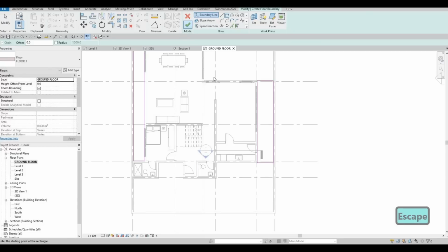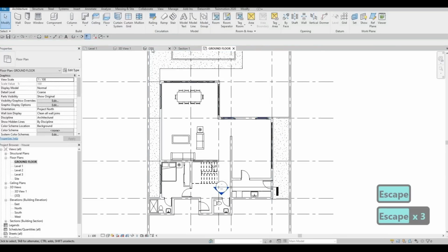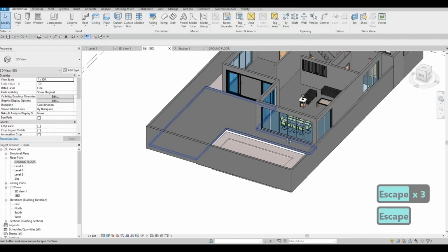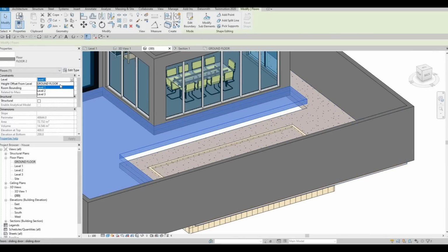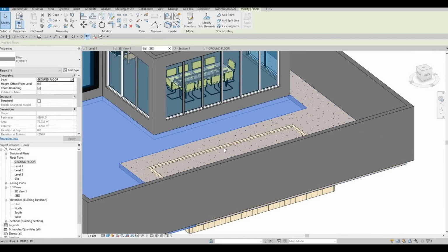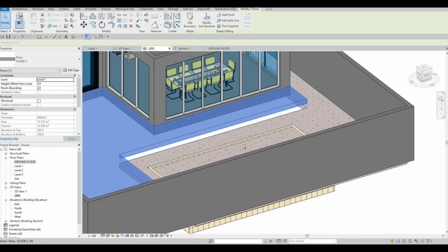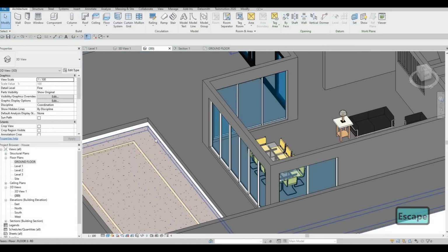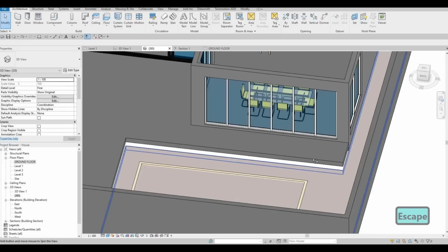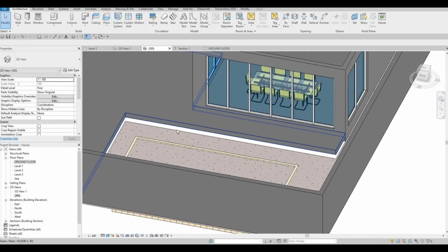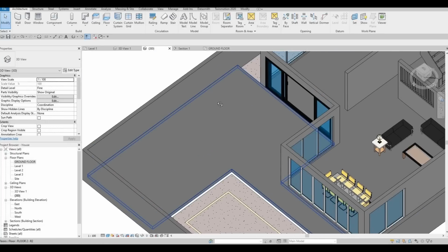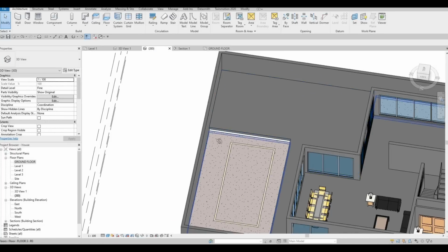And then click on finish, and then if we check it in our 3D, it will look like this because this is the ground. We have this one probably ground as well, but this one actually we need to put to level 1. I think that's correct. And then we just need to add another stairs right here on this side and this side as well.